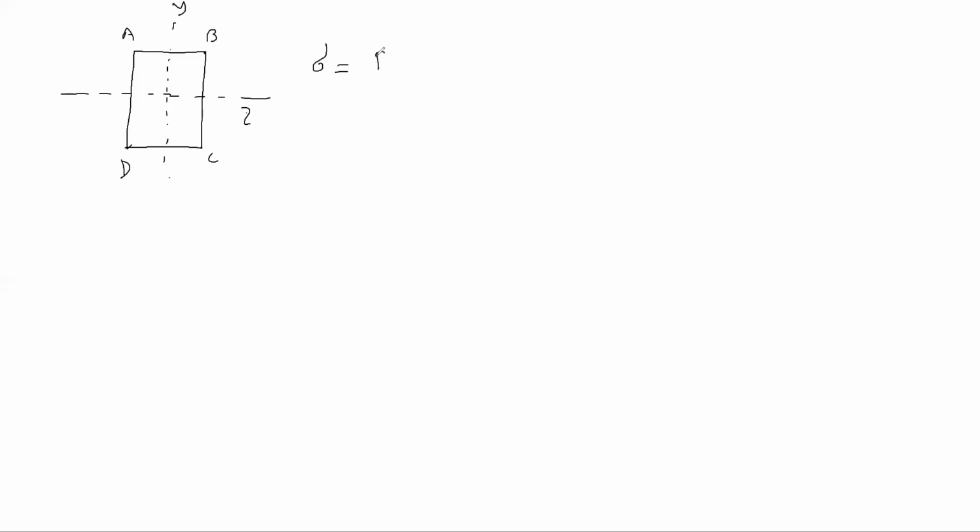The formula is P over A, plus MZ Y over IZ, plus MY Z over IY, and we don't know whether each is positive or negative. It depends on which point, right? The only thing we know is P over A is negative because the force is compression.